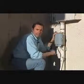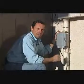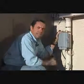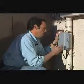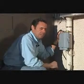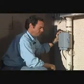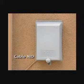Okay, the network interface device, or NID, is the box located on the outside of the house where the local service providers like the telephone company bring and terminate their service. The box is supplied by the local service provider, but you'll provide the cable that you need from here to the distribution device, and we'll show you how to do that later. Cable service companies also typically use an